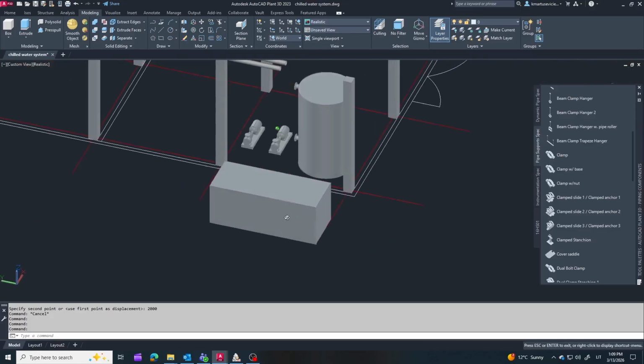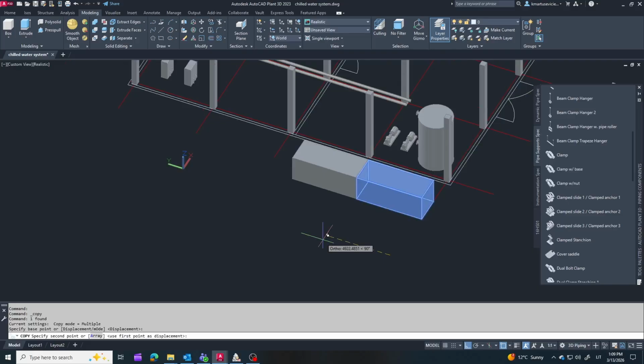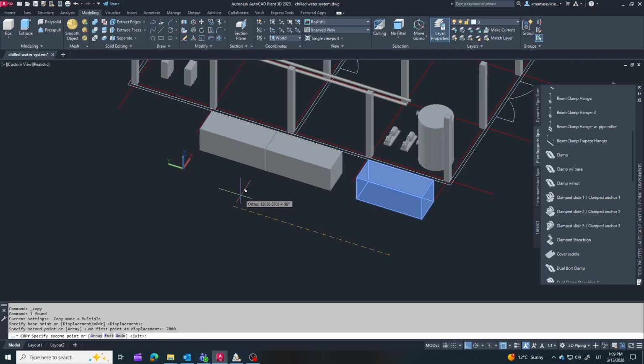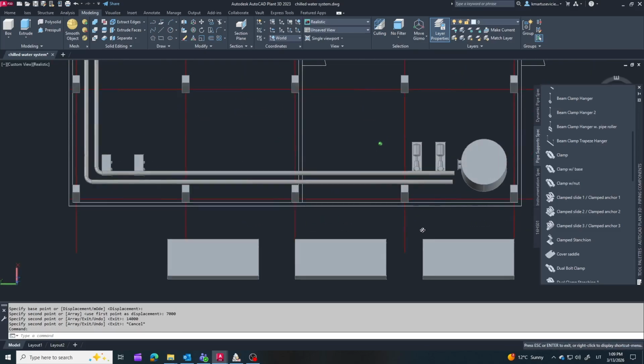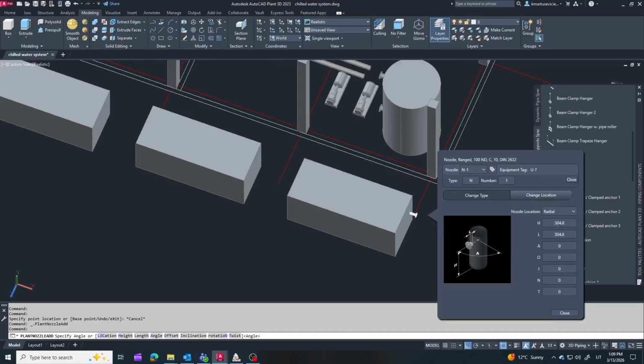This gives enough room for the chiller loop piping and also provides a walkway for access and maintenance around the equipment. The principle of this loop is the same as for the user loop. Water circulates through the chillers, where heat is removed and then returns back to the buffer tank.